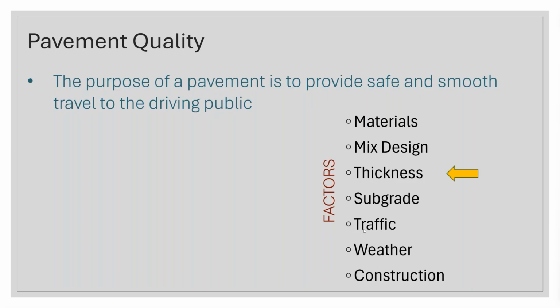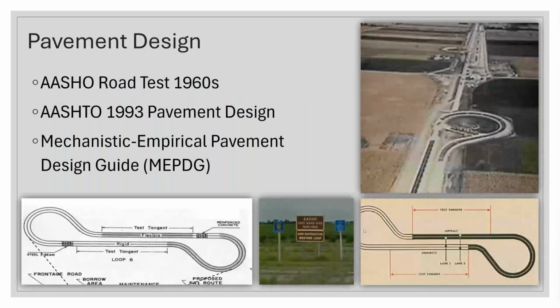So not what materials am I putting together, but after I get that part figured out, how much thickness do I need? The thicker the pavement, the more structure you're going to have. So we're looking at that in the context of how much support we get from the subgrade and how much traffic we expect is going to go onto the top of that pavement. And then, of course, weather plays a big factor, what part of the country you're in, what type of climate, extreme weather events, and then construction. Because construction always kind of gives us one little wild card extra at the end of the process.